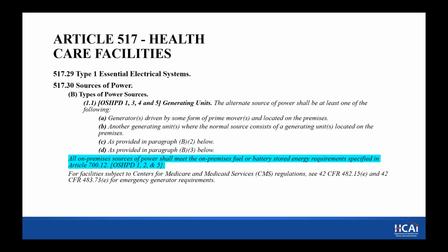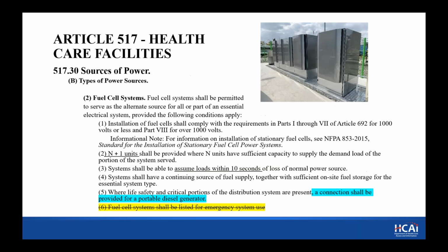And then we just have a pointer down here about, in order to meet CMS requirements, you do need to have a generator for your emergency source.